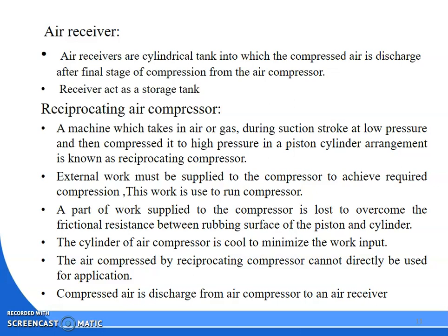If the air is at high temperature, it wants to expand its volume, but you want to compress its volume. Under that condition, you have to give more work input. Since the compressor is a work absorbing device, minimum work should be required so that efficiency will be higher. For that reason, we have to cool the compressor.